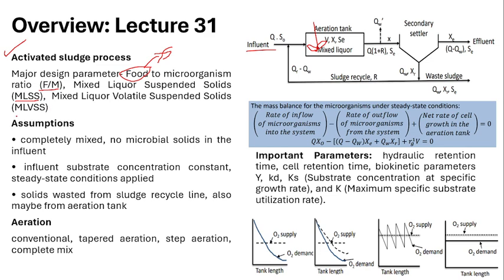Okay. The next parameter is MLVSS, the mixed liquor volatile suspended solids. A portion of this MLSS is taken up by the microorganism as food, and that is termed the MLVSS, the volatile suspended solids. All these things happen here in the aeration tank in this process.